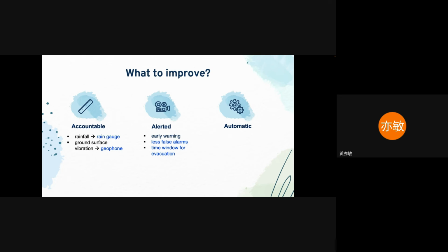They will pick up values from the geophone signals. So this could be a good tool to help us capture the occurrence of debris flow. And we want it to do that automatically, because whenever you detect any irregular signal, you will announce the warnings to the people.